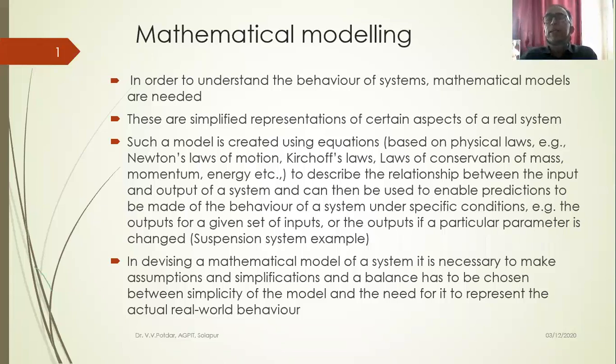And this is how we have to correlate this physical phenomenon with the law that governs that phenomenon, isn't it? So in the case of paintbrush, if I'm asked to develop a dynamic equation for this paint brush or painting activity, then I need to make use of Newton's law of viscosity, which is tau is equal to mu into dou u by dou y. This is just an example, every dynamic physical system.